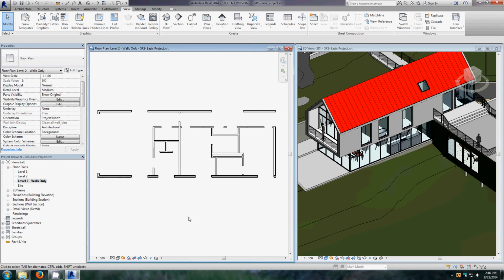So we're going to highlight this wall, this exterior wall, and notice when you do that, so for now make sure it's not highlighted. Click escape a couple times to make sure nothing is active, and just keep an eye on this ribbon up above, and notice it changes when I select the wall.